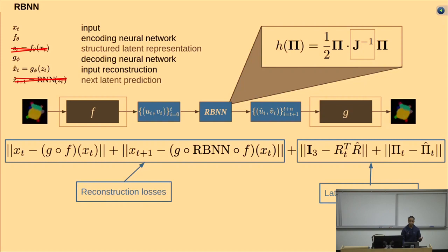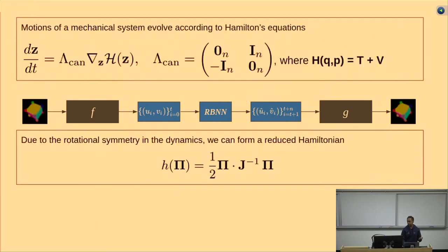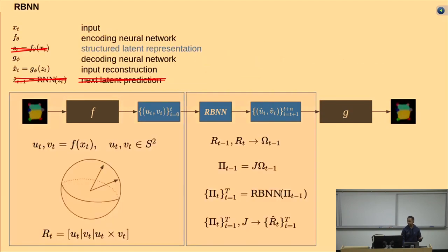Sorry, yes, but there's an initial angular momentum that you use to predict going forward in the dynamics. Oh, I see. Right here we have an initial angular momentum that has to come from somewhere. If it starts from 0, then we could hope it converges to the true thing as the sequence continues. This initial angular momentum is computed with some initial moment of inertia tensor.